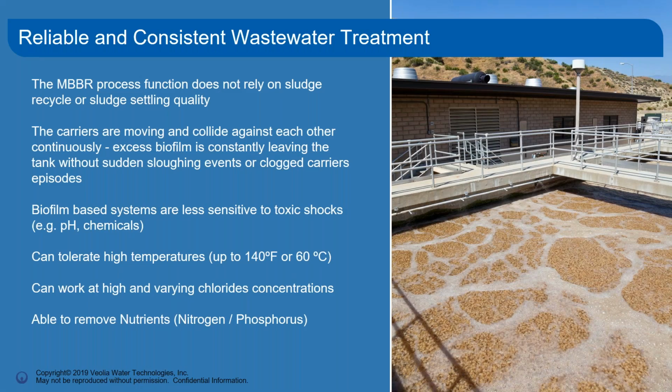What we can say from the experience we have now from more than 25 years of operation in this industry is that it's a very simple and robust technology. We are not depending on sludge recycle and the sludge settling quality, which is often a pain in activated sludge, that you have to follow and control to have the performance of the system.